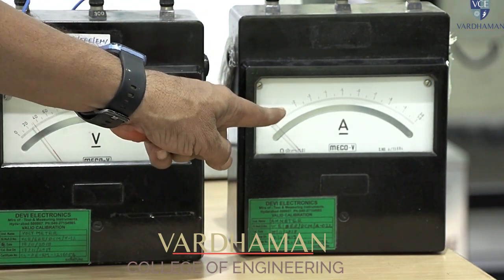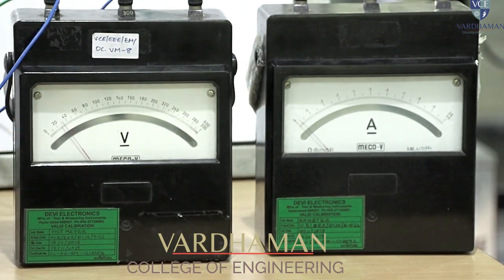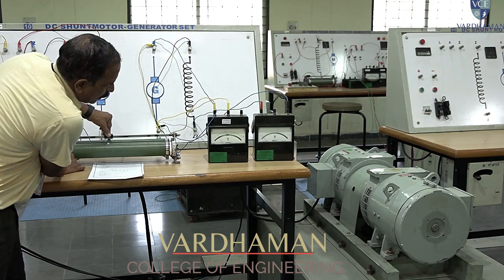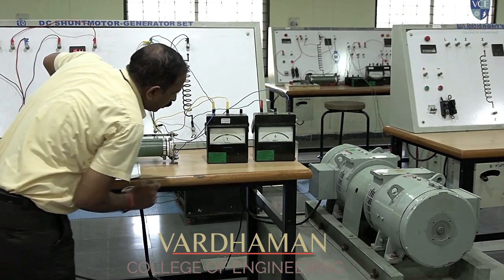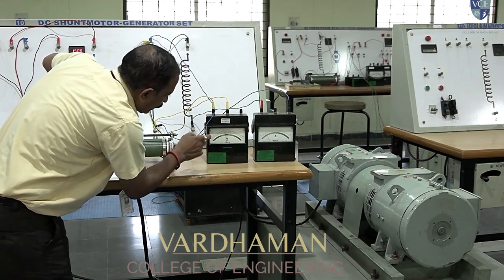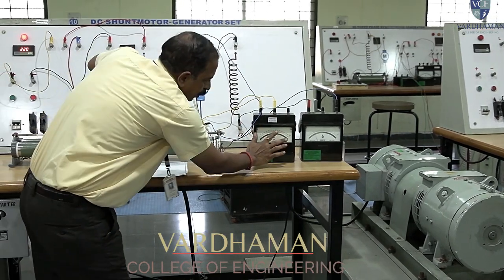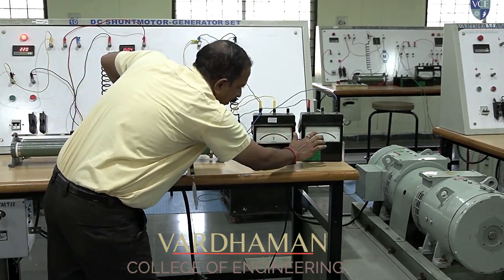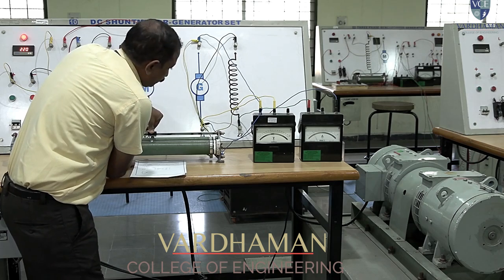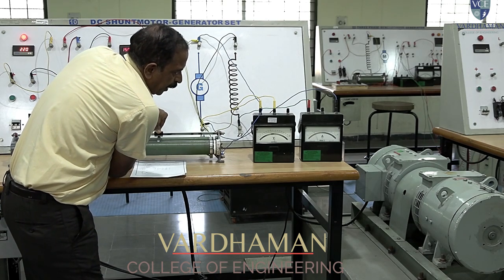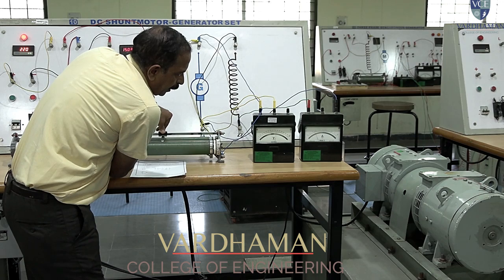Now please watch the ammeter as well as the voltmeter simultaneously. I will increase the current. You see the current is increasing. The needle is moving on current. As current is increasing, the voltage also increases. Our limit is that it should not exceed 220 volts. The current should not exceed 0.48. Like that we will take 4 to 5 different values by varying current.